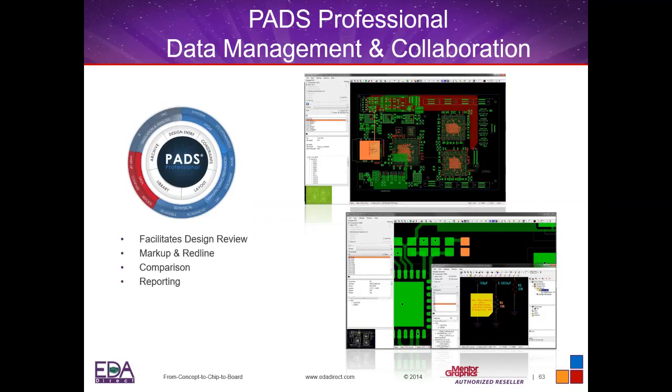I can do markup and red lines. Say I'm an engineer and I'm getting ready to do some spins. I can actually come in here and place some post-its to remind myself of things that I want to do on the next spin. You've got full reporting on the design. So it's a very powerful archiving tool that you should definitely use when you want to save a design to a certain level and maybe go off on a tangent and start experimenting on a design, but you'll always have this as the main one that you can always copy from and start over again.